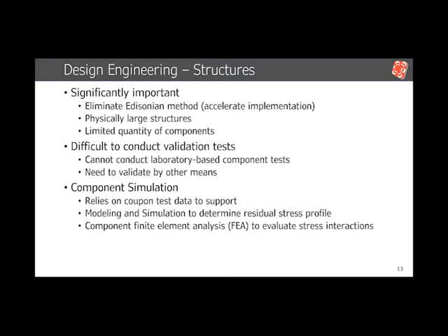The other area that's significantly important, we have some very large structures today that we're laser peening. We had William Sims from Entergy talking about the application of engineered residual stresses to the reactor head portion of the part to improve fatigue life. Those structures are large enough that actually doing a component fatigue test on those is difficult to do, and there are not very many of them. There are limited quantity of those types of components, so being able to conduct a test on that is difficult.